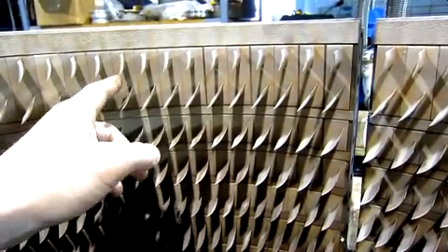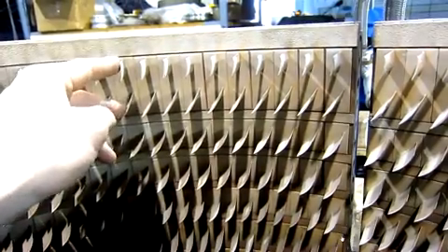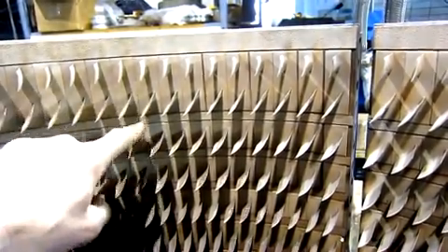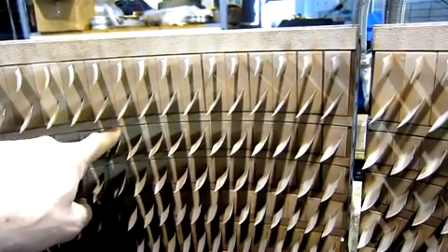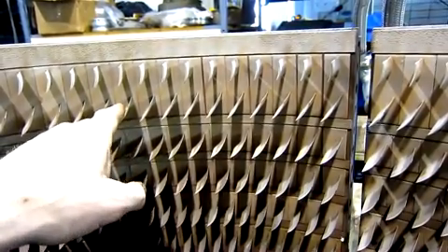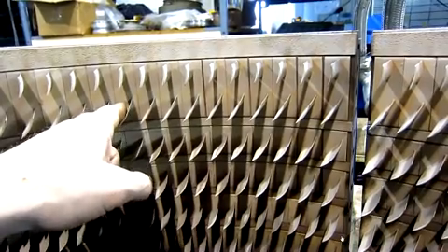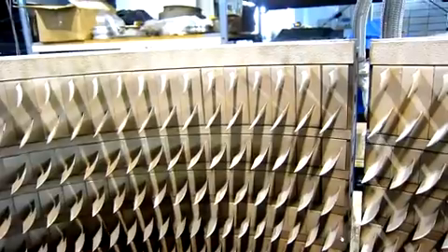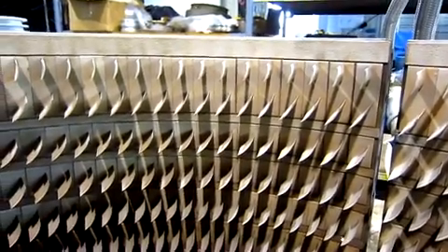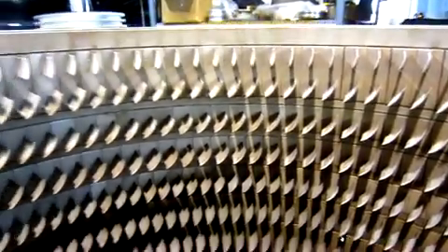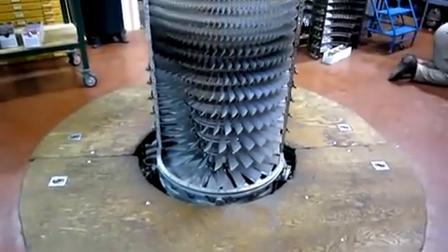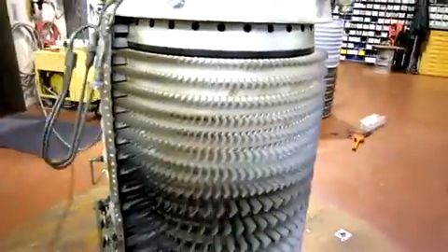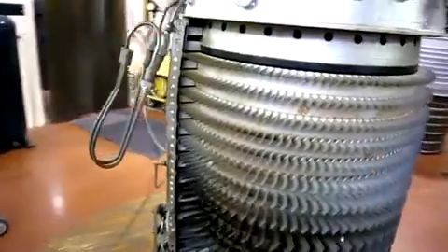Outlet guide vanes. This is a two-piece design. There's no rotor stage in there. The 17th stage of the rotor is here, and the air contacts this stage, or sub-stage, I guess, and then this one can be directed straight back into the diffuser, which we covered recently. I like the way it looks with a case half off. Pop the hood, so to speak. Look at that. Look at all the stators lined up with the...